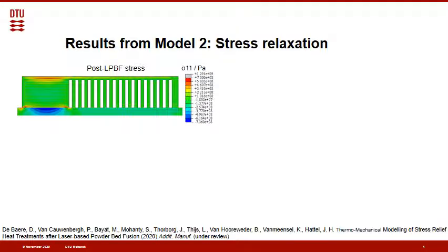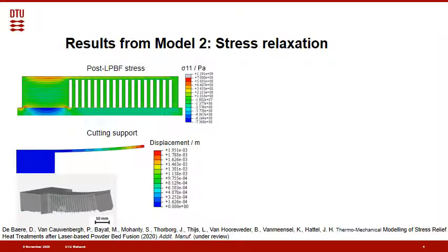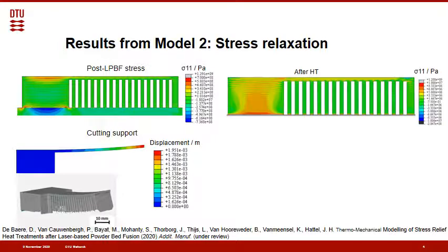Moving on to model 2. This is the stress field that is used as an input for the heat treatment simulation, which was validated using actual experimental measurements. After the heat treatment, the residual stresses are significantly lower. If I can focus your attention for one moment on the scale bar on the right, you can see that the residual stresses are 2 orders of magnitude smaller, approximately.